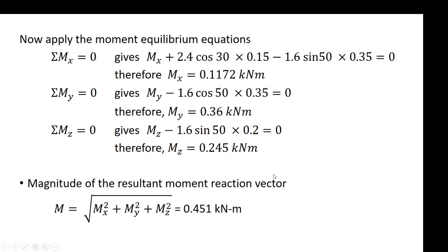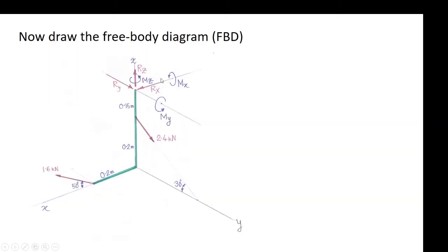You can also apply the moment equilibrium equations in statics, and then you can find out the moment components. Now, here, students, you might not be familiar with the reactive moment you have drawn there. So do not forget to include it into the moment equilibrium equation with proper sign. You have assumed a positive sign with respect to the right-handed system.